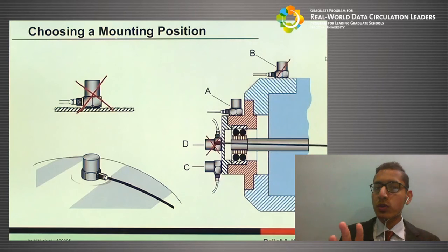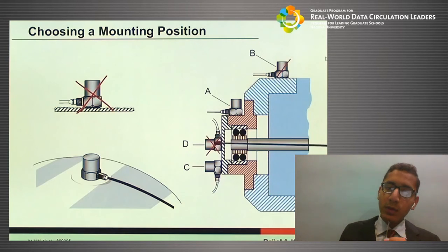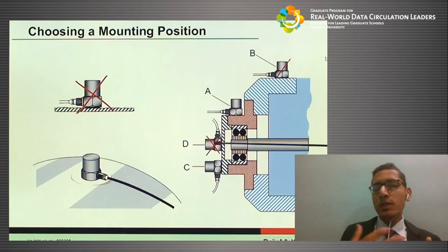It will not note the proper vibrations, so we do not use the B position. Now at the C position, it is away from the line of action and closer to the vibration, so C is applicable, but D comes straight in front of the vibrating body, so it will hinder its motion. It might even cause a resonance. It will give us more problems than our required solution. So the reasonable positions for mounting will be A and C.